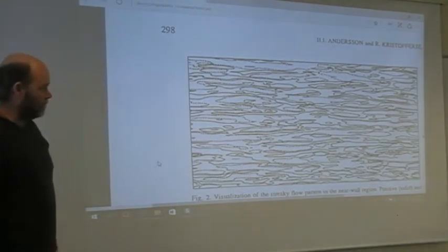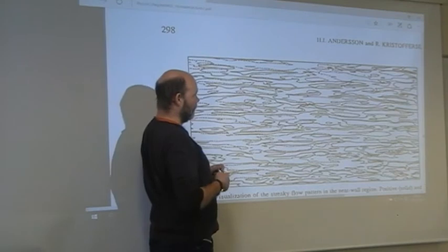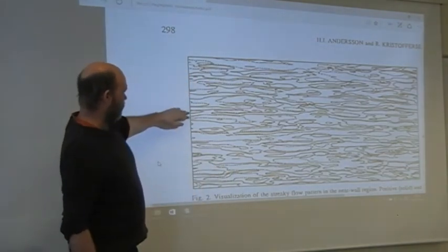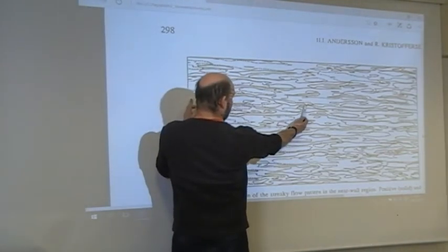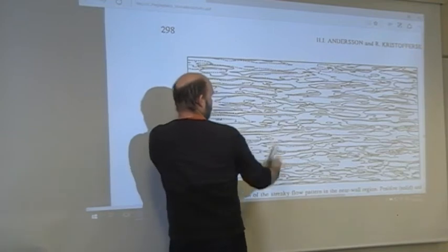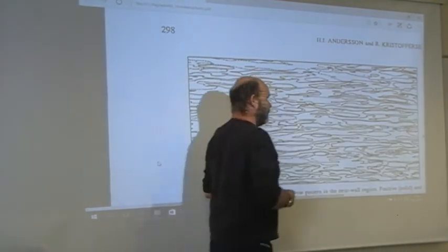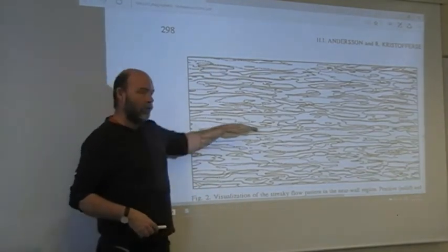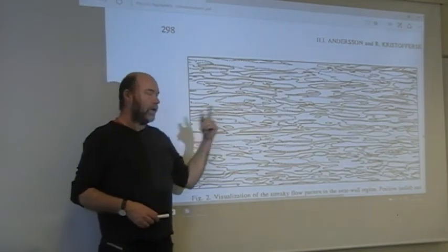But if you choose a domain that is not long enough, if you look at the longest streaks here, how long can they be? Well, fairly long. This one is so long, and also it continues here. That's sort of getting dangerously long, because if you have one structure that goes through the entire domain, you will have sort of a self-amplification due to the periodic boundary conditions.